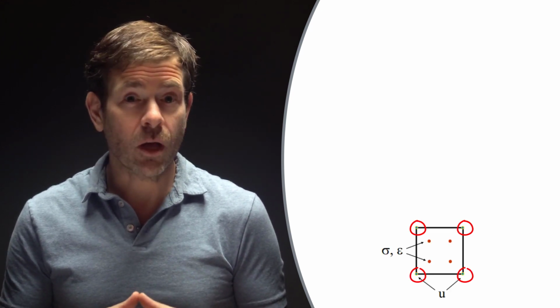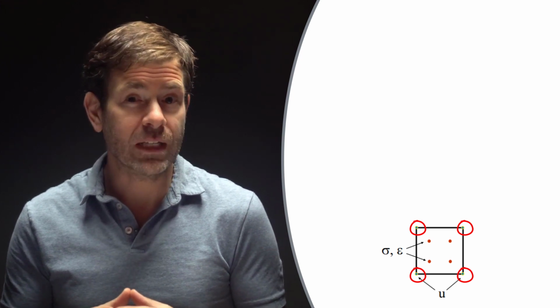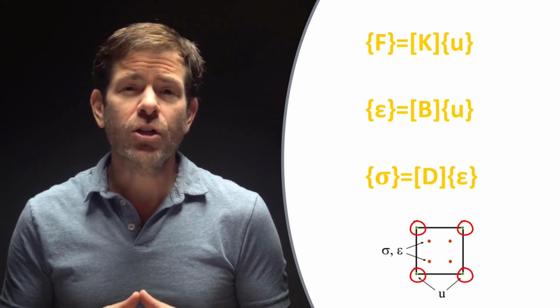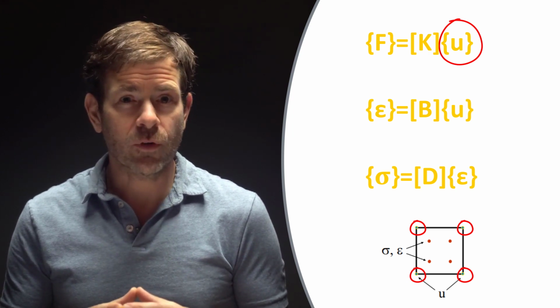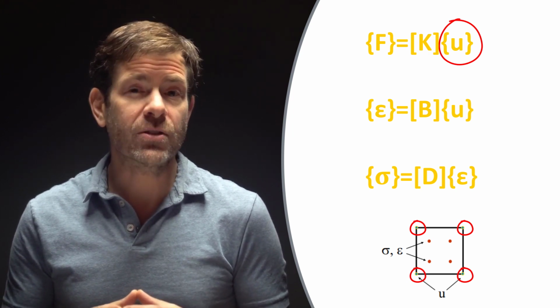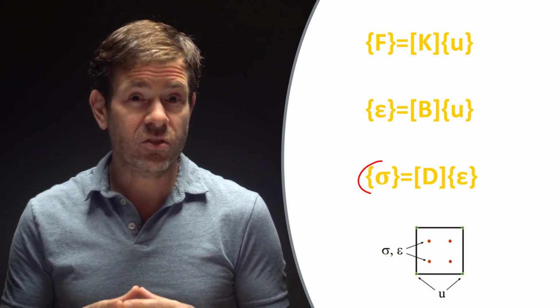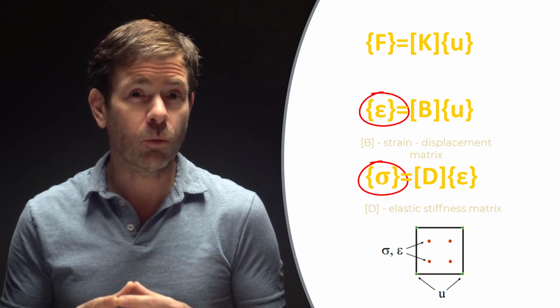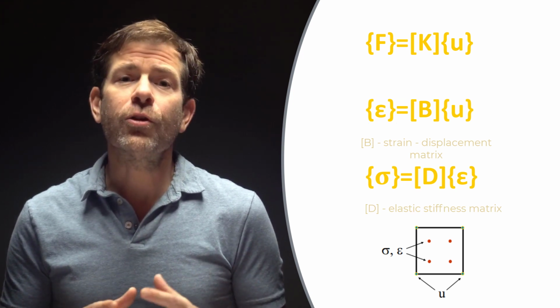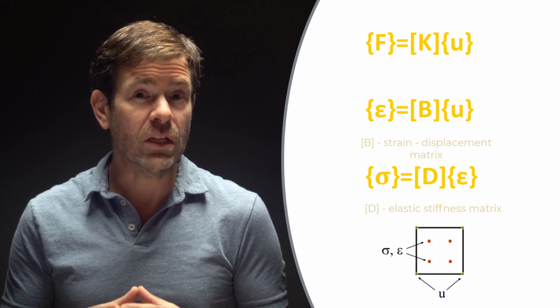Let's investigate when and why these occur, but first recall that in structural finite element analysis, we're directly solving for the displacements and rotations at each node. These are the unknowns from the global matrix equations. These quantities will always converge to a unique solution as the mesh is refined. The stresses and strains, on the other hand, are derived and they're not calculated directly from the global matrix equations, so their values may not converge to a unique solution with a finer mesh.